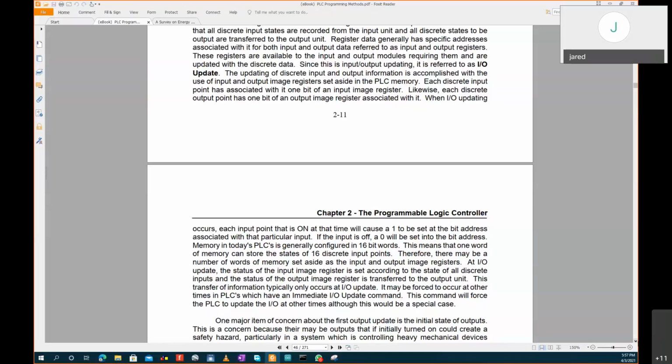So, solve the ladder. After the I/O has been accomplished, it has checked all the inputs and outputs, analog, digital, whatever it is, the PLC begins executing the commands. These commands are typically referred to as the ladder diagram, and the ladder steps use relay contacts and coils. The ladder is drawn with contacts to the left side of the sheet and coils to the right, like the relay-based control system.